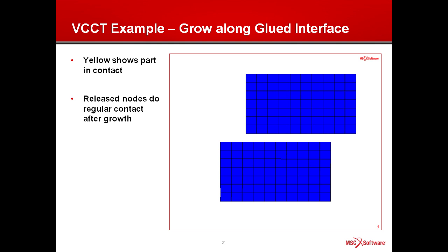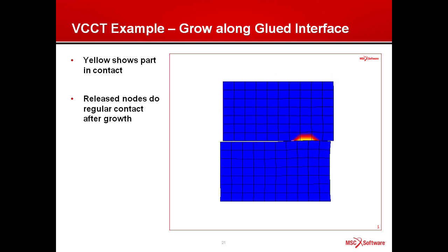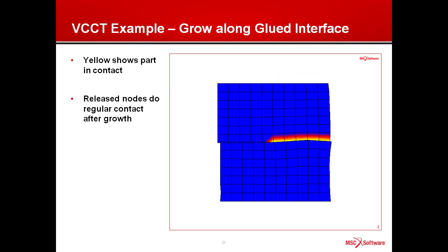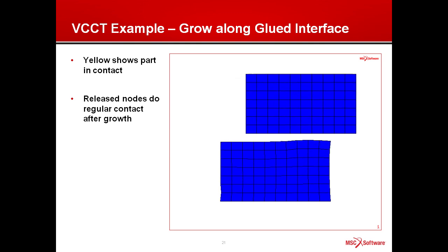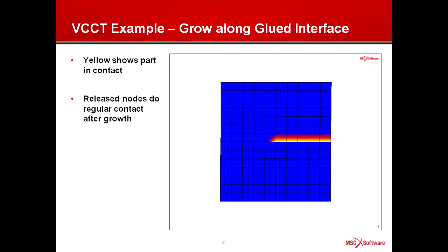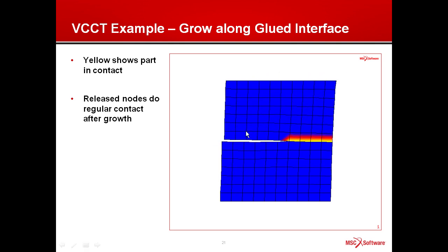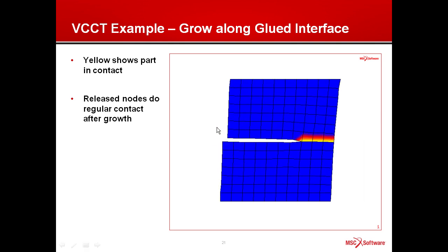And you can see here the crack, or the delamination, is occurring. This is a combined mode 1 and mode 2 behavior, because you can see the two parts opening up, that's mode 1. You can also see them shearing apart from each other, so that's mode 2.